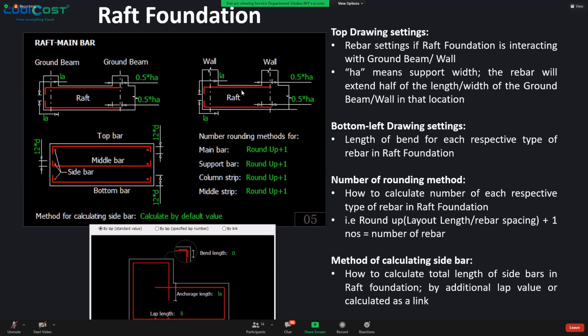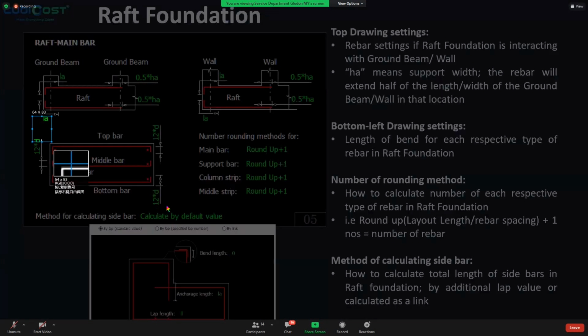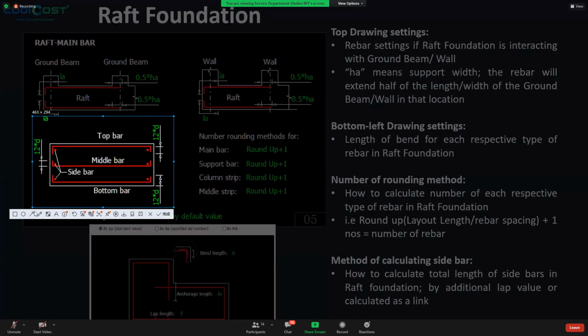But something else different here is because instead of using cantilever slab, we don't have cantilever slab now. Ground beam, the one is not called cantilever slab, it's just a suspended slab that has no support towards the edge. Because the raft foundation itself is the support. So that's the situation. So in the event that that happens, same like just now the cantilever slab, you will have a separate calculation here that you need to change for the bending, which is this one over here. And this one. Right? Very straightforward.